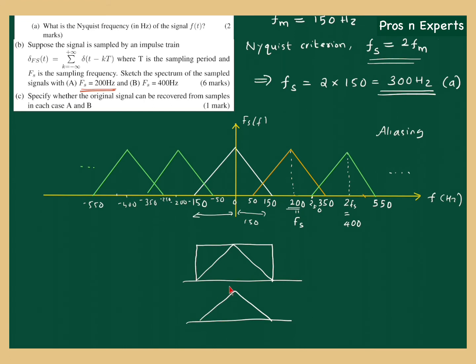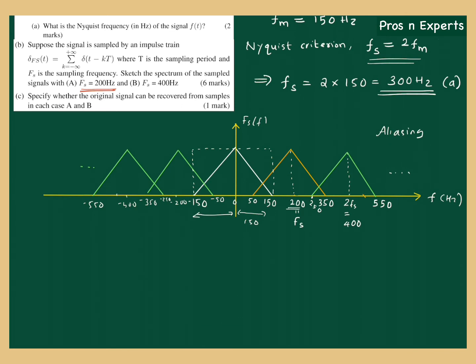You will not recover the original as such, because what you are going to encounter is multiplication with this signal in the frequency domain, and what results is not that triangle but something extra, some spurious components from other replicas. So instead of this triangle, you will get this thing, which is not our message signal, so the reconstruction is not faithful. Okay, so this is called aliasing.